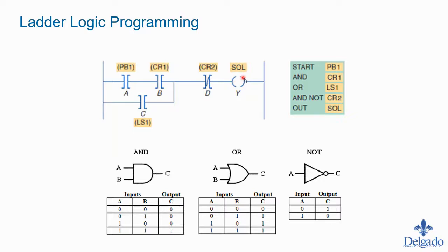This is two parentheses, so to speak, but this represents a coil. So this will be considered an output, right? So the contacts could be considered as inputs, not always the case. The coils will be considered the outputs. That's not always the case either, but typically this could be an input from the field, and this is an output to the field, basically.